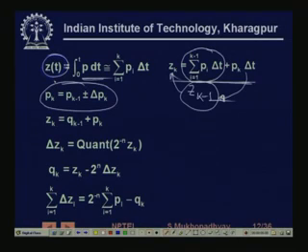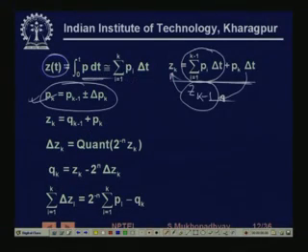In the case of linear interpolation, it need not be changed, because every time we are adding the same constant p. But if you want to have some other kinds of interpolation, like circular interpolation, or exponential interpolation, then we need to change this p. So we actually have this fixed length register q.